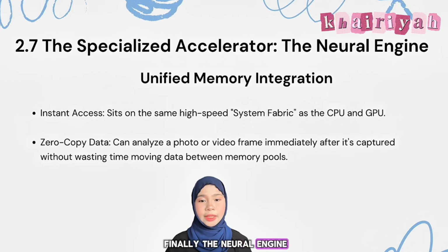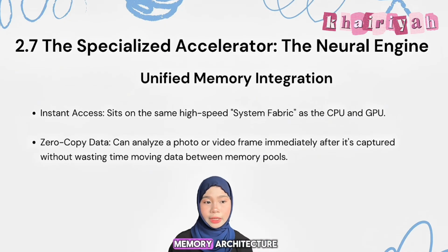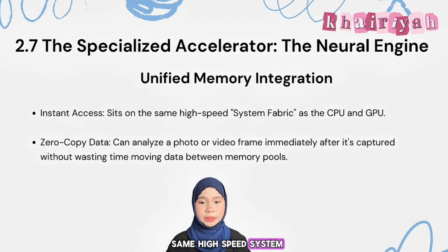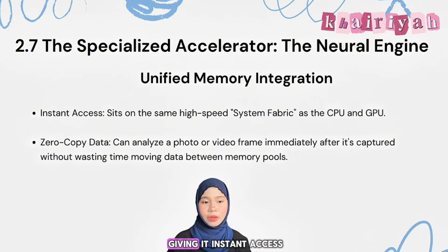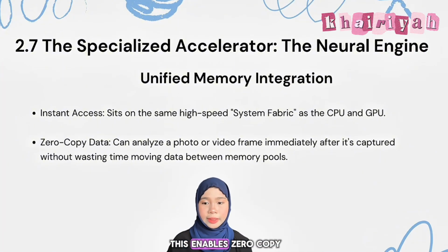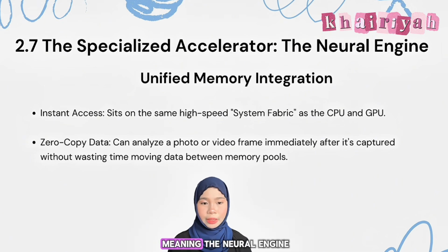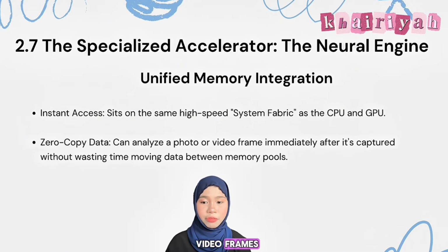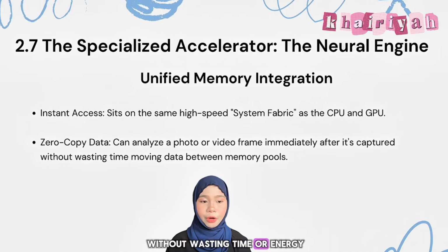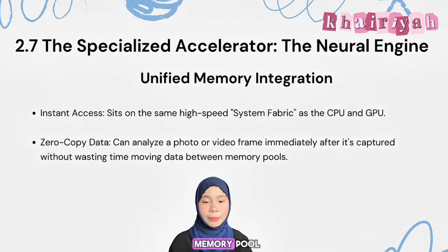Finally, the Neural Engine is tightly integrated into Apple's unified memory architecture. It sits on the same high-speed system fabric as the CPU and GPU, giving it instant access to shared memory. This enables zero-copy data access, meaning the Neural Engine can analyze photos or video frames immediately after capture without wasting time or energy moving data between separate memory pools.